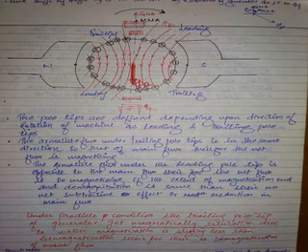Now, depending on the direction of rotation, you are going to define the pole tip. Means from this point to this point of a south pole is called the leading pole tip. The first pole tip in the direction of rotation, first which it meets. For example, this is the direction of rotation. South pole is here. The first pole tip in the direction of rotation when it meets is known as leading. The next pole tip is trailing. Similarly, this pole tip is leading.